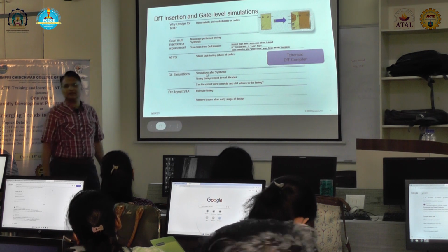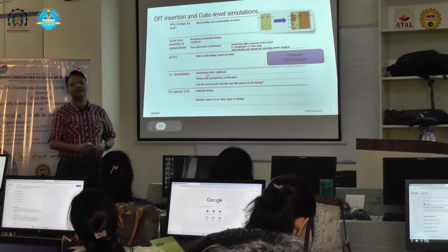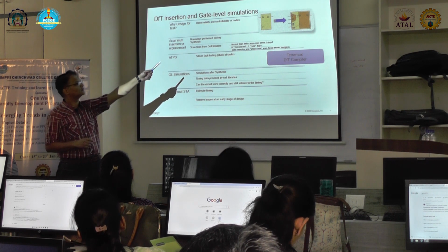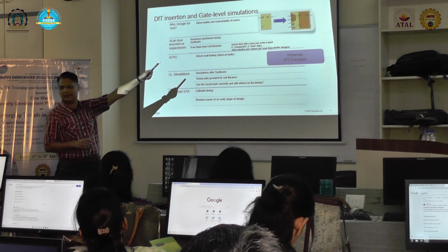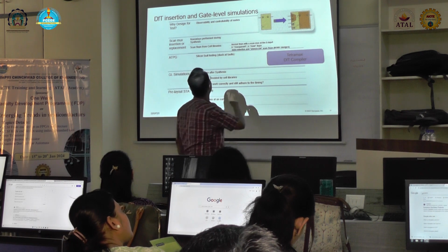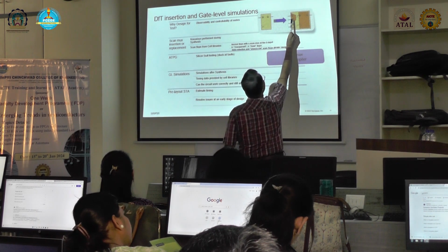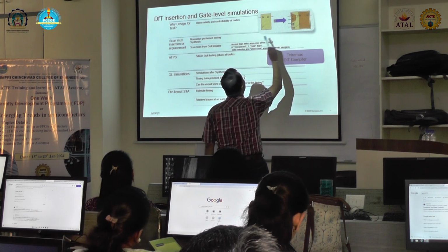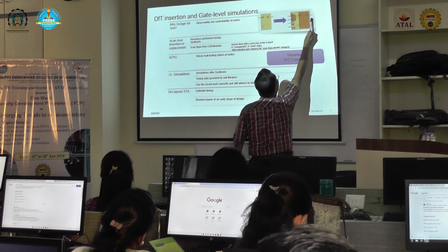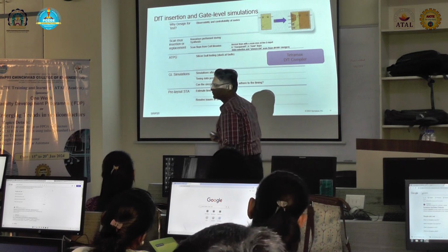So let us put it this way, DFT is adding that scanmux, that multiplexer. When you do DFT insertion, you are actually adding the scanmux. But when you do ATPG, you are actually toggling this input and observing this output.